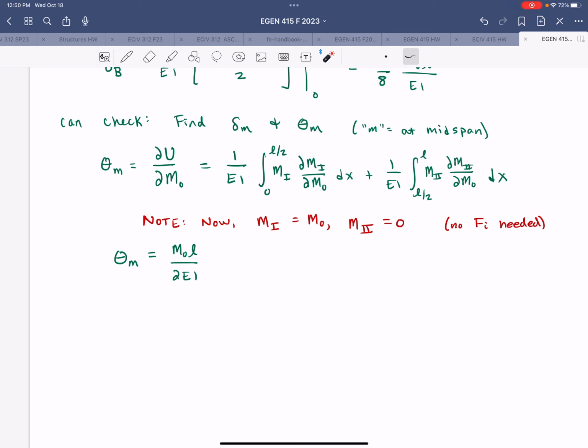Oh, one second. Yeah? Sure. Because I thought that for this first part of question 1, it'd be easier to calculate the stress with force over area instead of the moment y over I. But I think you get a different answer if you do it that way than if you just do force over area. Okay, remind me which problem this is. This is the composite section.